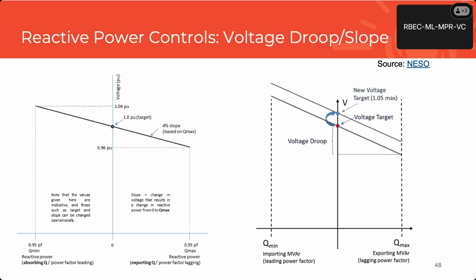Okay, can I share this? Okay, so maybe I'll figure out a slide later. I'll draw you a slide of how this works in the control loop. So if you're doing a PID controller or a PI controller, you can add a droop parameter back. It's a feedback gain from the output of the PID back into the summation block going into it. Okay. So that adds into the error for the PID. Okay. That is how you implement the droop.